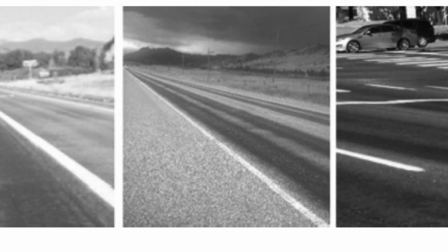Bleeding is a flushing film of asphalt binder on the pavement surface, looking like a shiny, glass-like reflecting surface, as shown in Fig 8.8, that can become quite sticky. Bleeding areas have less skid resistance, that is, they are slippery, especially in wet weather. Bleeding is not a reversible process. This means asphalt binder accumulates on the pavement surface over time and does not go down.